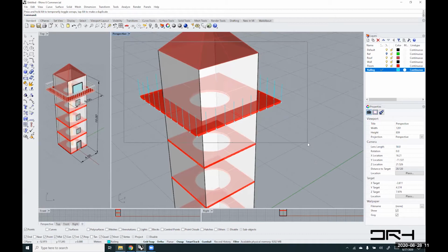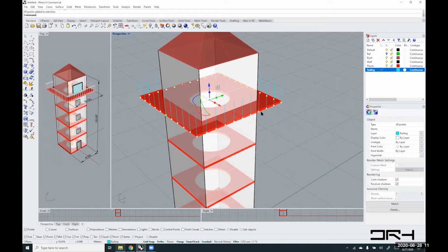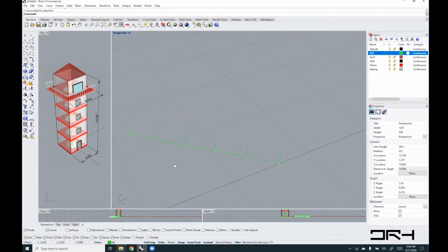Now, if I window select, it will select only the points because the curves in the selection filter are not turned on. So I needed to click on the curves as well and window select. It selected all my points and curves, and I can move them all together to my reference. Remember, my reference is turned off, so this is why they didn't show. Once I select my curves, I can create a pipe command.